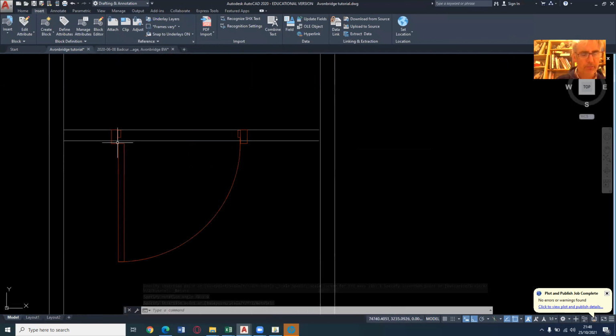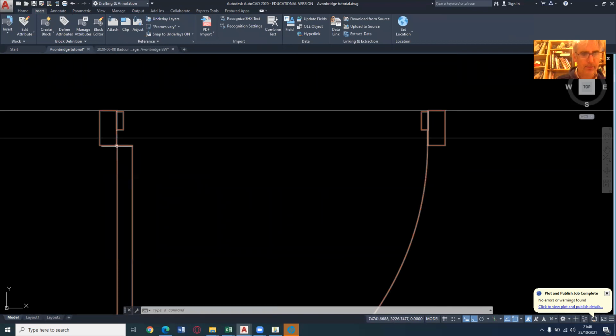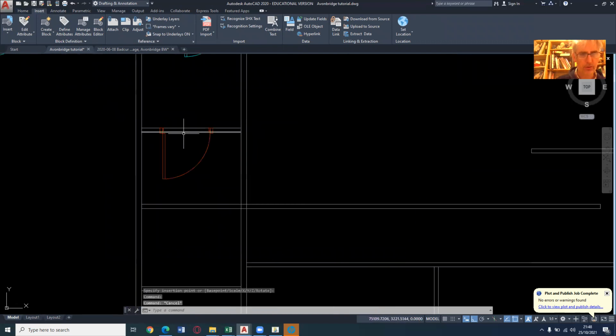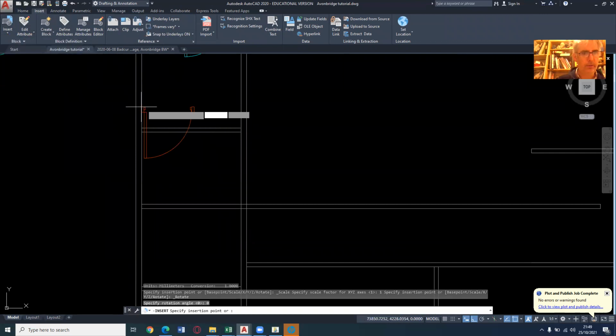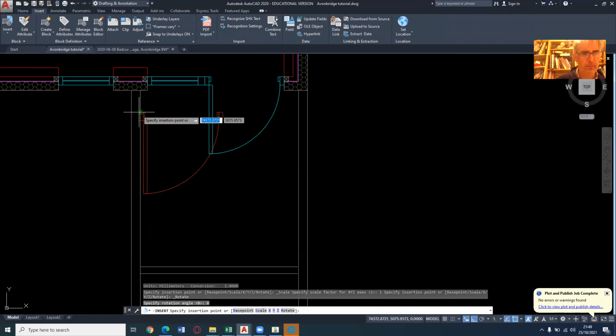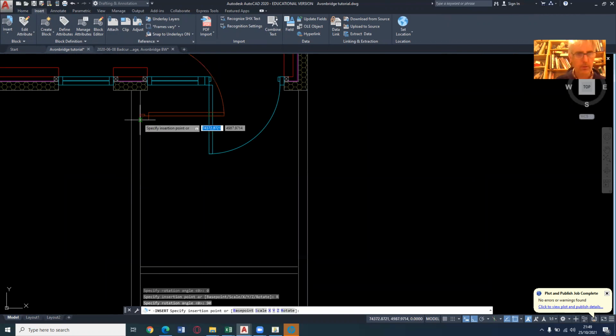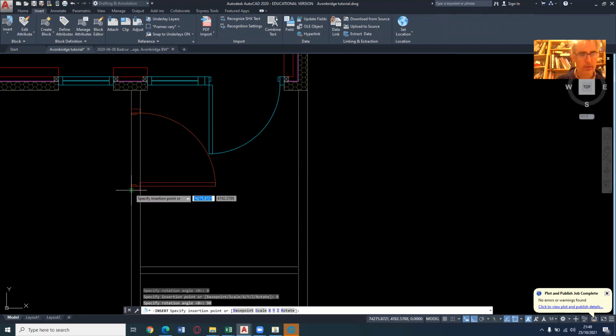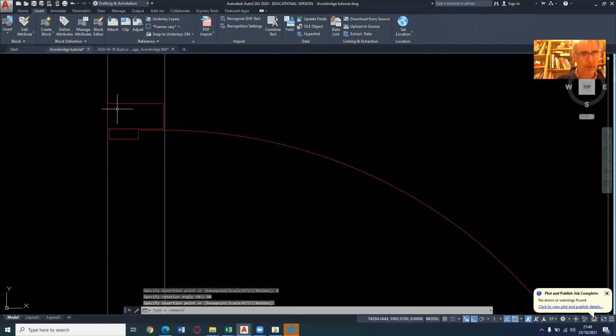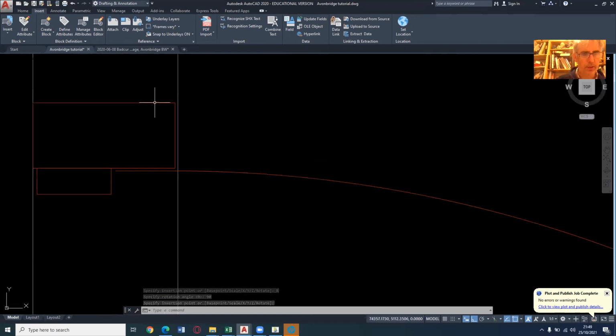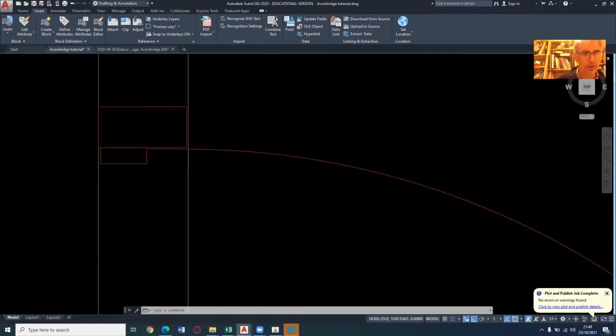Now that one there, I've made for a 95 thick partition. So I'm going to have to do another door. That's okay because I can use that one for this wall. If you remember, I'm going to click on rotate, and click a rotation angle of 90. So I could click it there, and it fits in quite nicely. Not too bad. I think that was 97, which is why we're getting a bit of a difference. That's okay, we're all right with that.